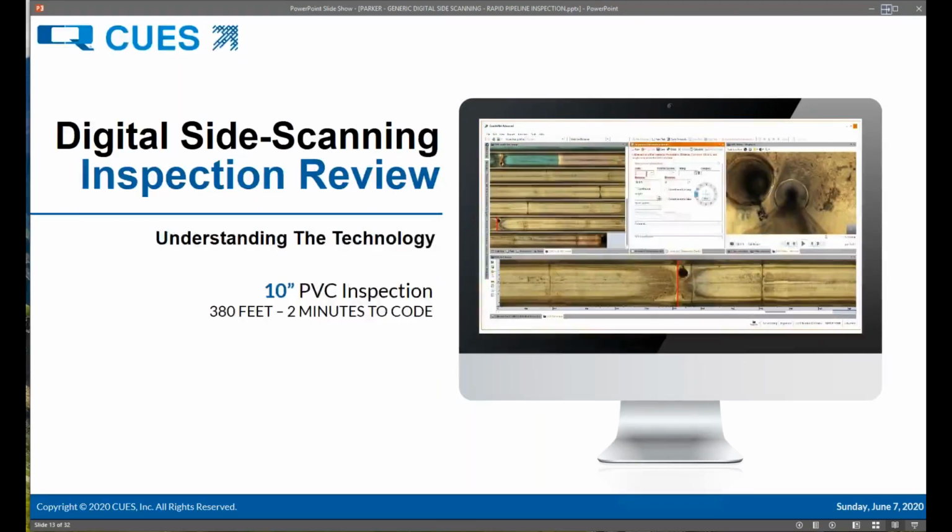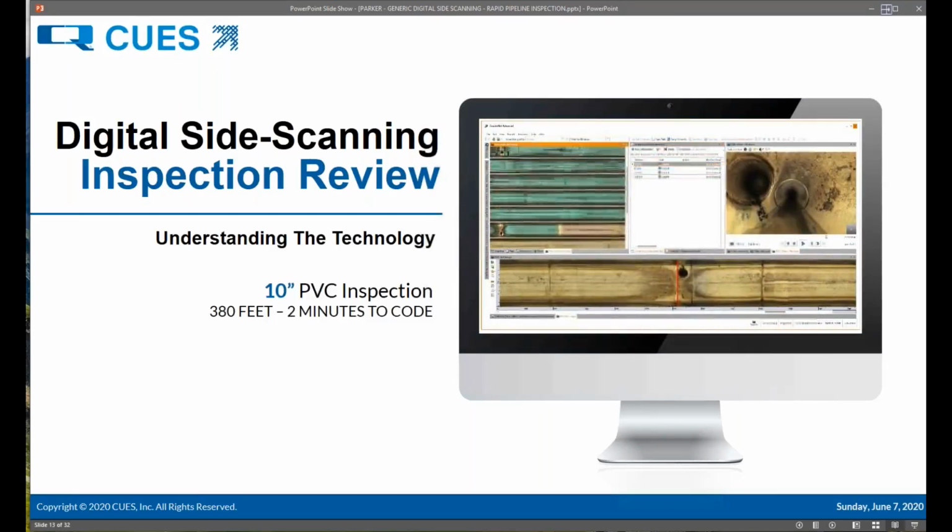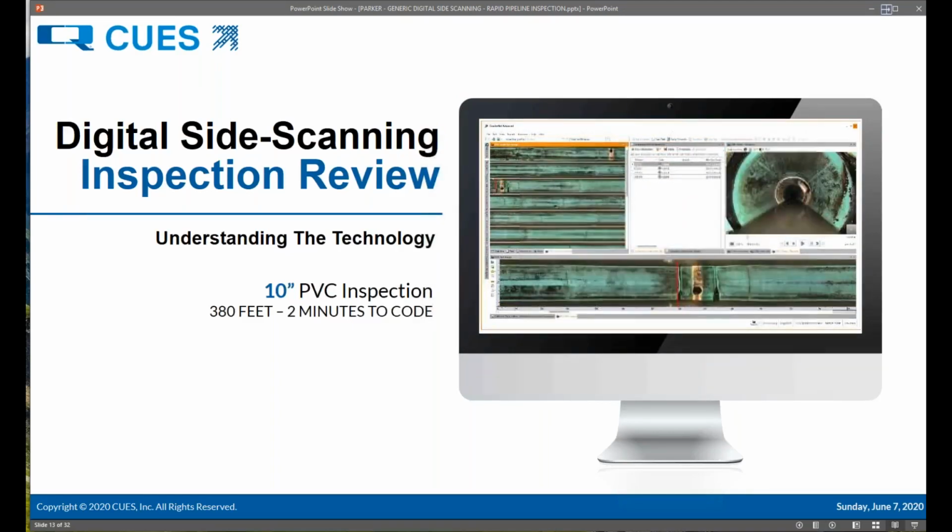But as you can see there, in a matter of a few seconds, we coded all 4 laterals. We can give it the code, and of course, this is NASSCO compliant as well, if you did want to use NASSCO coding versus a standard coding system out of the box with any inspection software. But all in all, 380 feet, 2 minutes to code, that's really hard to beat, even with the best operator using pan and tilt technology.